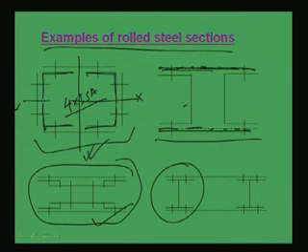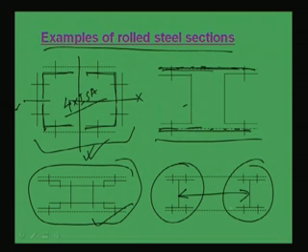Another section, say 2 I sections, we can provide with some distance, so that the Iyy becomes more. Okay, so if this is the Y direction, then Iy becomes more. That means we have to make this spacing in such a way that Iy will become equal to Ix. The moment of inertia of the whole section about the X direction and about the Y direction should come close together to get equal resistance from both sides. That means to get the optimum placing of the sections, so that we can get the maximum benefit from the section.